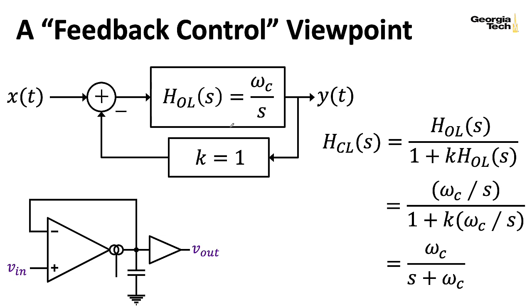Well, maybe you would be representing these things in terms of voltages and currents. And oh, very conveniently, an OTA has a differential voltage input, so it has an input sitting here facilitating that negative feedback. And conveniently, what do capacitors like to do? Well, capacitors like to take information represented as currents, integrate them, divide them by C, and then spit out a voltage. And what does the OTA like to do? Well, the OTA likes to take the difference of voltages here and produce a current where it takes that difference and multiplies it by the transconductance gain.